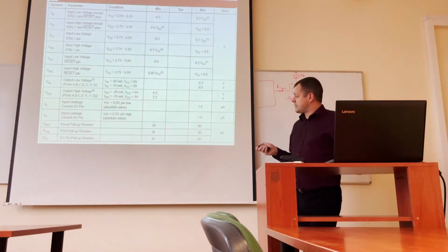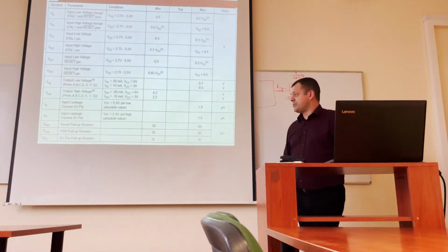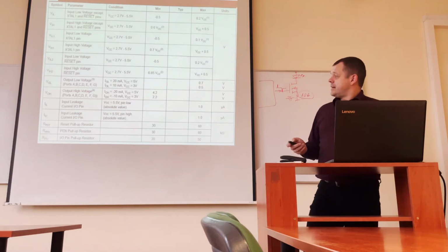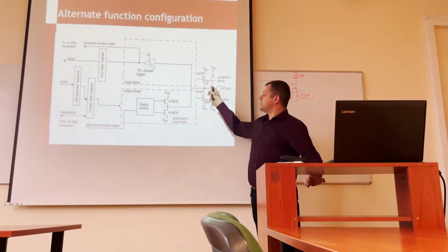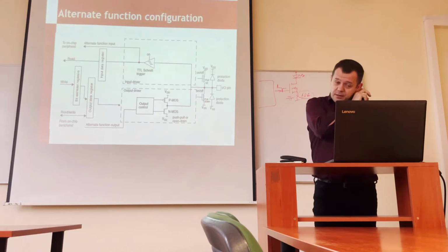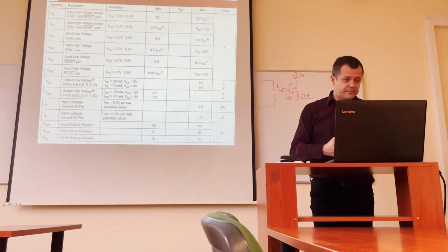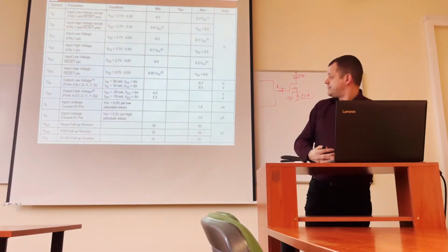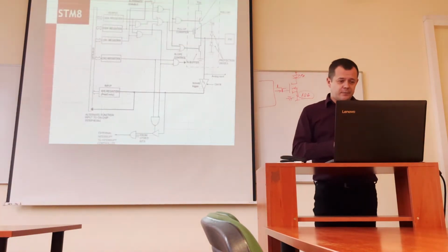And the last parameter that you can see here in the table is the various versions of the internal pull-ups, and what their values are. Not very precise pull-ups and weak pull-ups, because normally our external pull-ups are 4.7, 2.2, 10K. Here they are very weak pull-ups, but still a very nice extension. If we talk about the pull-downs, those values are similar. You can usually expect tens of kilo ohms. Here not very precise values, something between 20 and 30 and 60 that we can expect here.